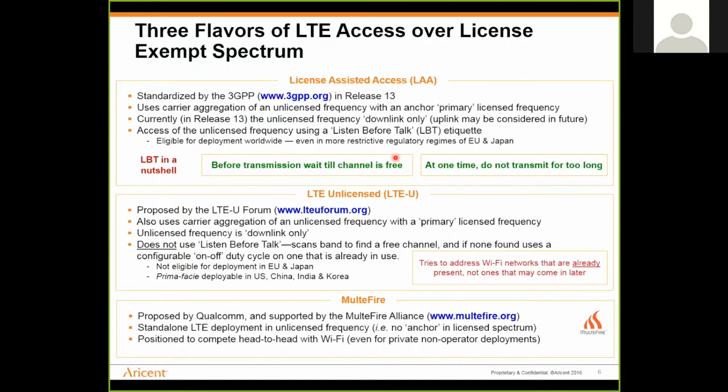So I keep talking about LBT. So what is LBT? LBT is basically 2 things. It's a bit of a politeness protocol, which basically says that when I have anything to transmit, I sense the channel to figure out that it's free, and only then do I transmit. And once I start transmitting, I don't hog the channel forever. I do not transmit more than a particular quantum of time at one time. Now, that quantum in Japan, for instance, I can't exceed 4 milliseconds. In Europe, it's like 8 to 10 milliseconds, maybe a bit more, depending on what exactly you're doing. But that's what LBT is in a nutshell.